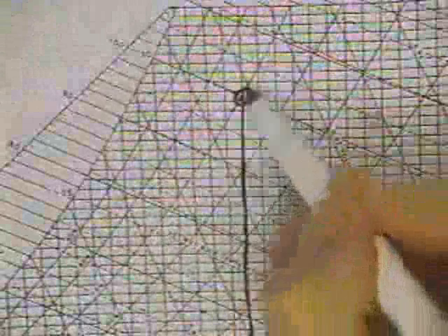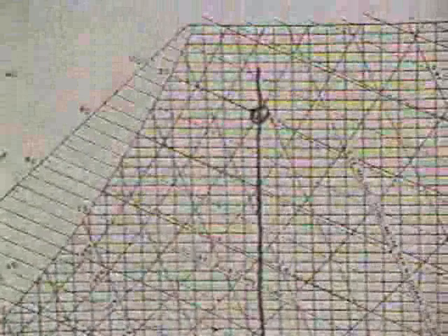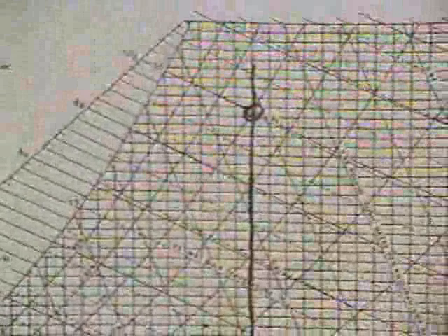In this case, we're looking at 35 degrees centigrade, so we're following the dry bulb temperature line up at constant conditions until we get to a relative humidity of 70%. I keep going until I get up here to 70%, and this is the point right here. The 70% constant RH is this curve that goes along here, and the dry bulb temperature of 35 degrees C intersects with 70% RH. So we have a very high moisture content. However, this is something we can read directly off the chart.